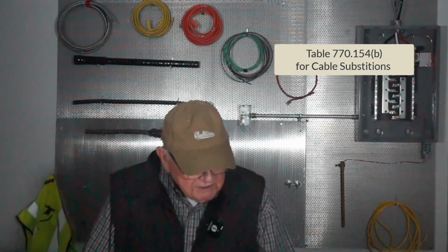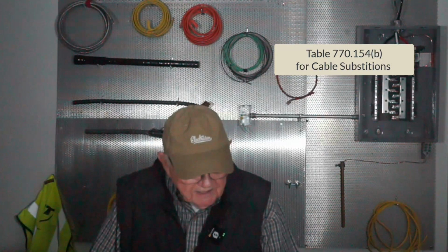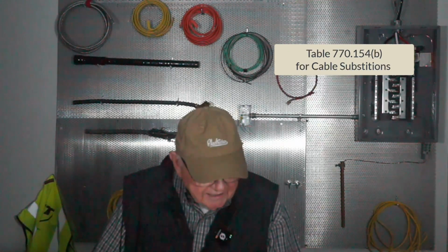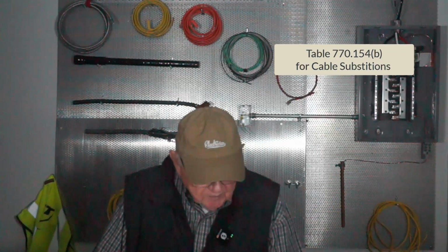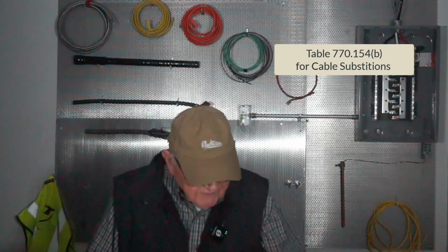770-154B is cable substitutions. So for instance, if I'm going to use OFNP cable, there is no substitute that I can use other. If it calls for OFNP, that's what I got to use. On the other hand, if it calls for OFCP in my application, a permitted substitution is OFNP. So pay attention to that one as well. Okay.